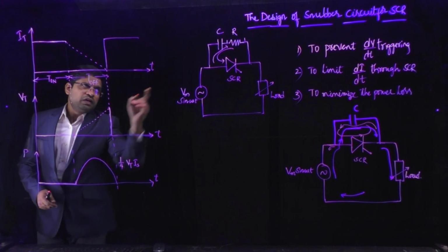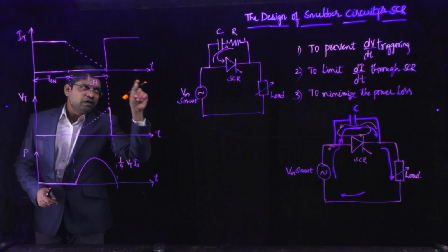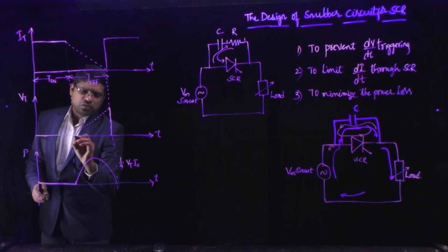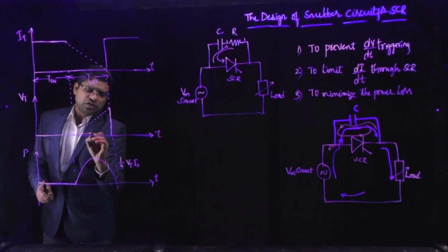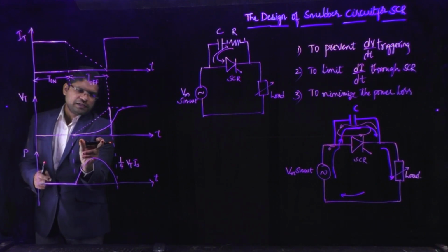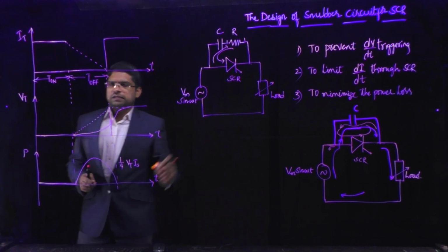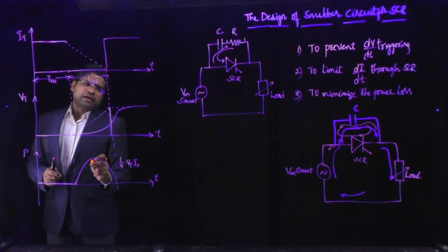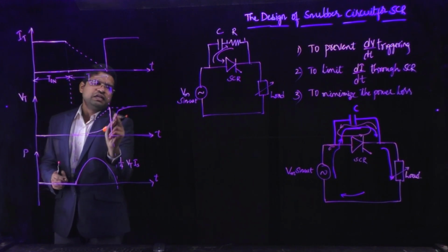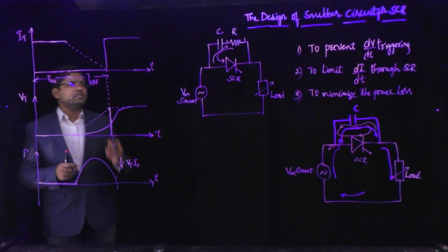Without a capacitor in parallel, the voltage changes suddenly, but because of the capacitor connected in parallel with the SCR, there will be a slow rate of change of voltage across the SCR. During turn off, current is reduced, but the rate of change of voltage across the SCR increases slowly, with no sudden or high rate of change of voltage.